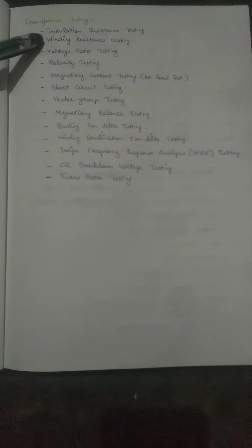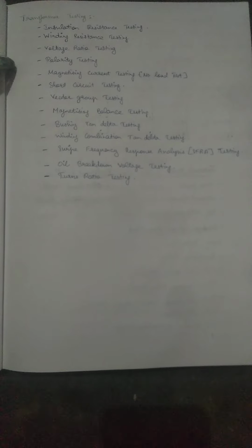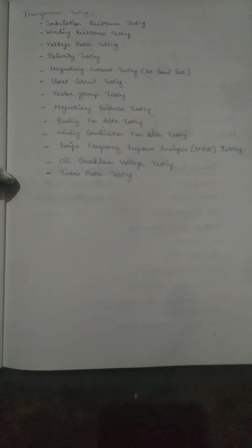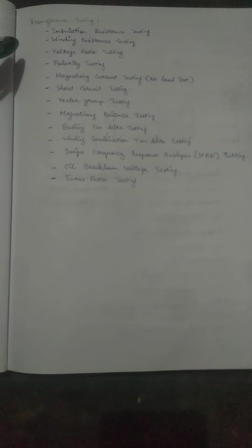Normally the basic thing is that first we need to characterize the testings as AC and DC tests. Mainly the insulation test, winding test are DC injecting tests. The remaining are mostly AC voltage injecting tests only, because in DC there is a chance of some voltage getting charged in our winding itself.